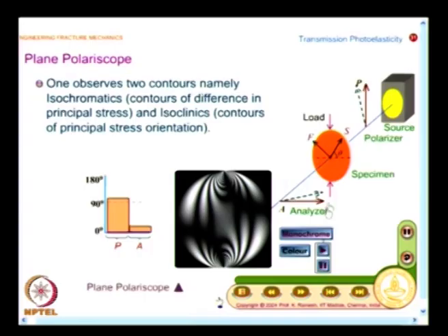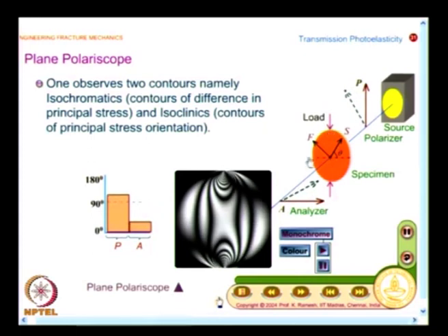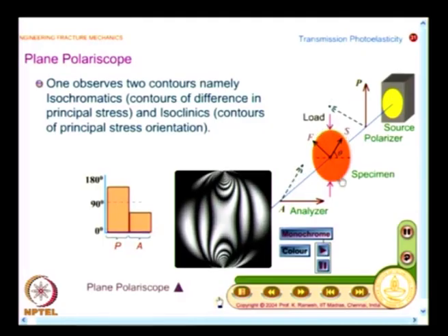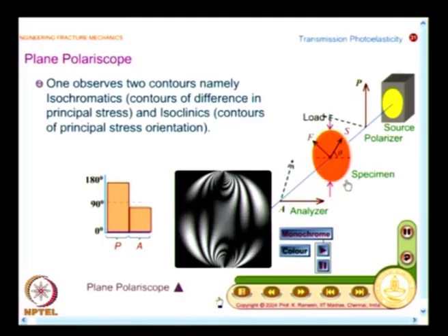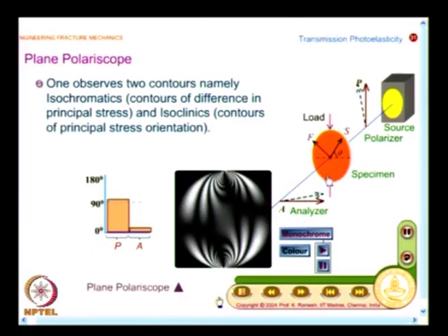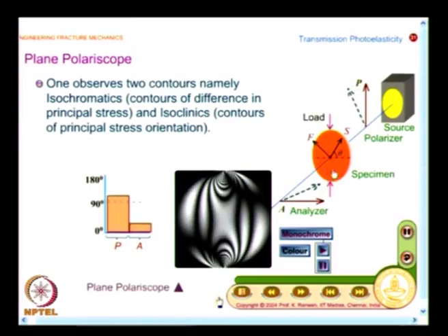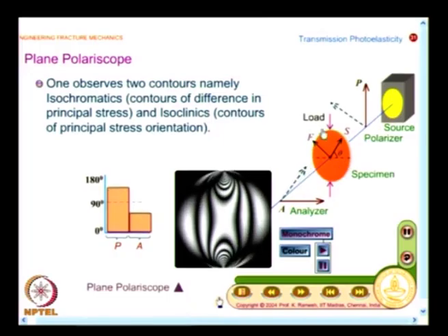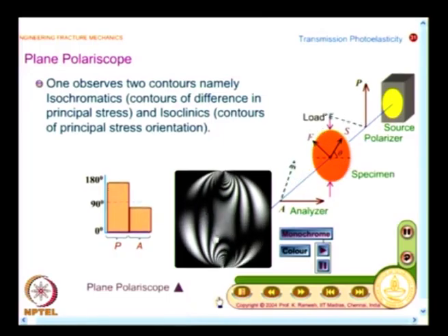So, we take an example problem which is good enough to illustrate all aspects of the technique that we are looking at, and we have taken a circular disc. If you look at a circular disc, what you need is a perfectly circular specimen, and if it is put between two horizontal platens, then a diametric compression is easily initiated. And not only this, the stress field is very simple; I have an analytical expression for the stress field, and I see isochromatics as well as